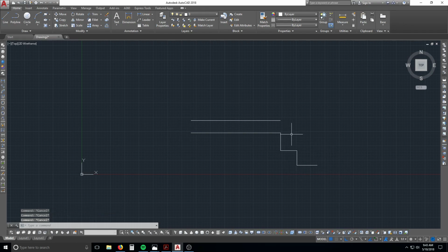So to rotate, let's say we want to rotate, again escape, getting out of all that stuff, we're going to RO enter, and to rotate, that was a left click. I'll do it again, RO enter, left click, drag, right click.